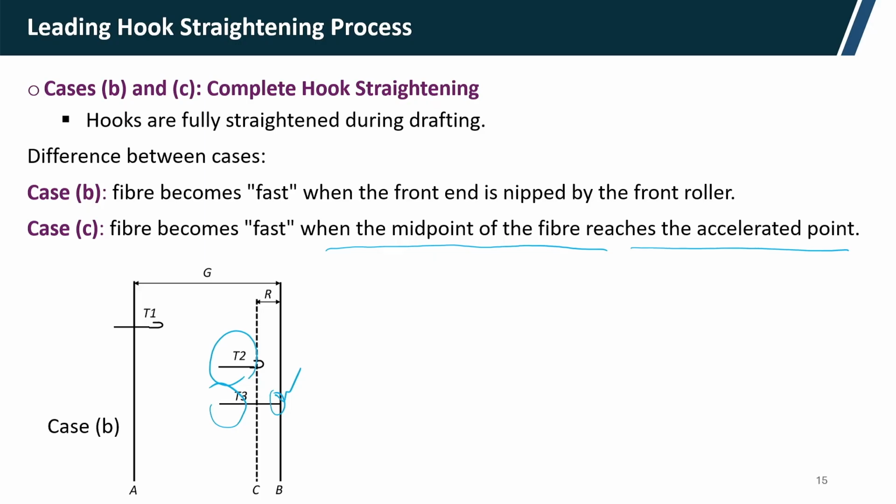before the mid tip fiber leading end is gripped by the front roller, the fiber starts moving at the front roller speed. It will move fast because the midpoint of the fiber body reaches the accelerating point.